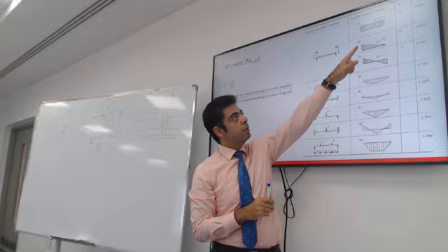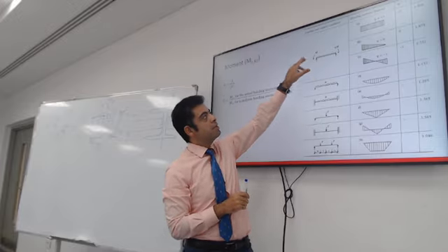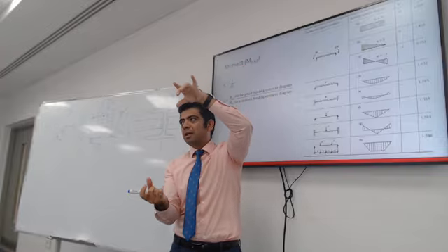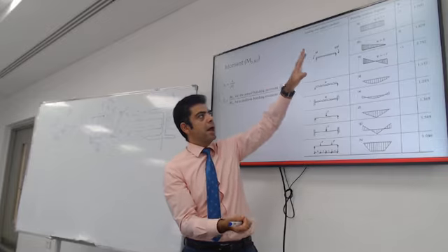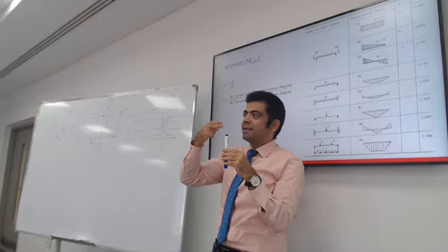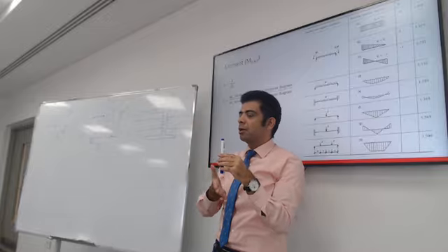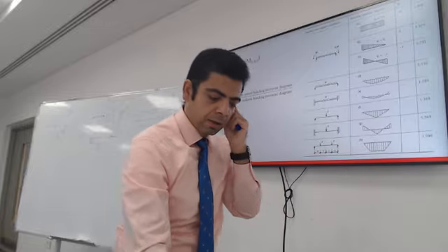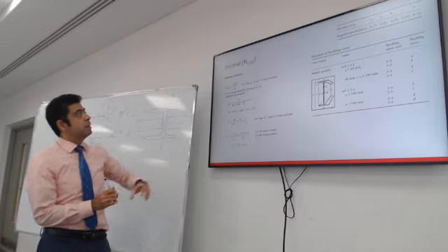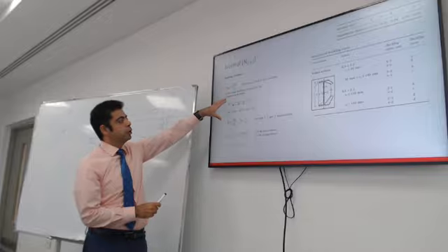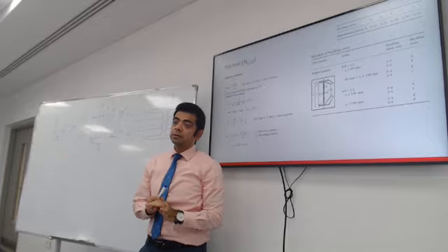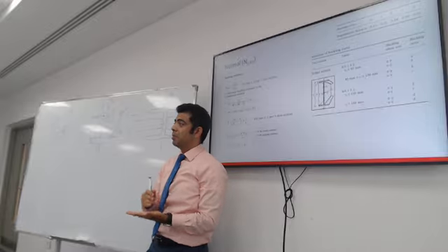For C1 to equal 1 means the moment is linear. There is eccentricity at the top, and maybe there is no eccentricity at the bottom. The moment diagram is linear, and you don't need any of that. If the moment is just due to eccentric axial load, the moment diagram will be linear, and then you're not going to need this slide. This is the normal capacity, including the buckling effect. We did that last week, how to calculate the axial capacity of the column.